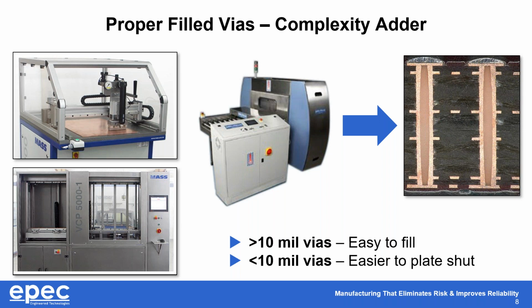One of the ways around that a lot of times is that we work with the customers to reduce the overall size of the filled via, and then we can plate it shut. That takes away this whole process. Does it take a little bit longer in plating? Yes, but it takes a lot less time than it does to properly fill and cure these filled vias.